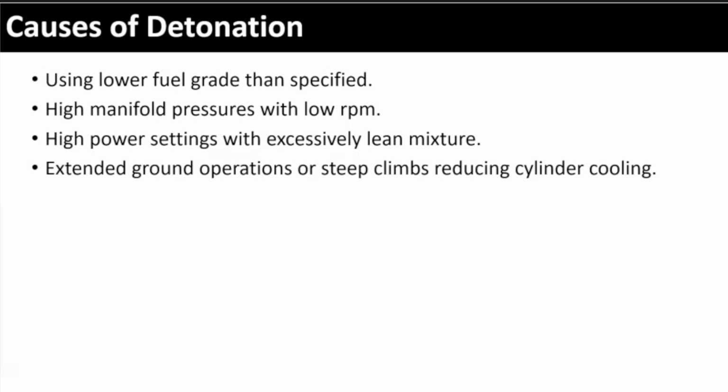Airflow, right? You're at that climb speed, which is not cruise. You're much slower than a cruise speed, so that airflow over the engine isn't enough to keep it cool. So a lot of times detonation could be caused because your engine's running hot, just because you're in a long climb and not keeping that engine cool.